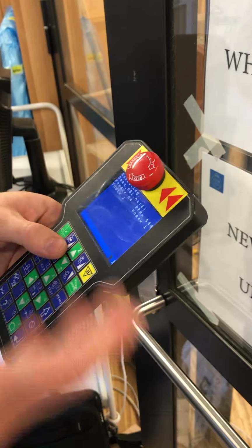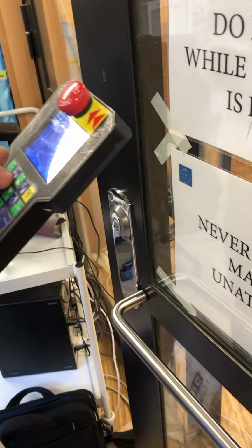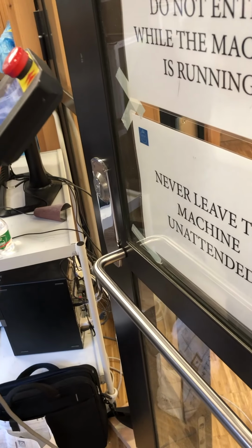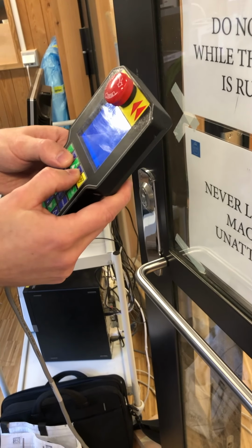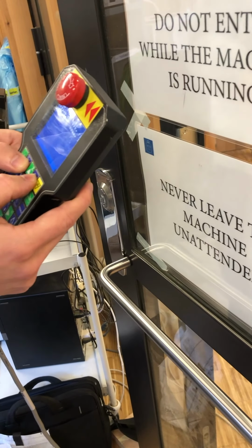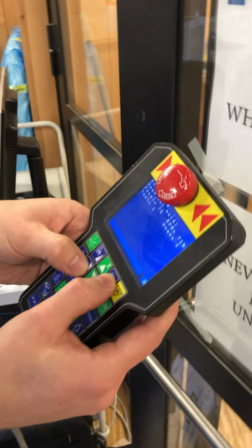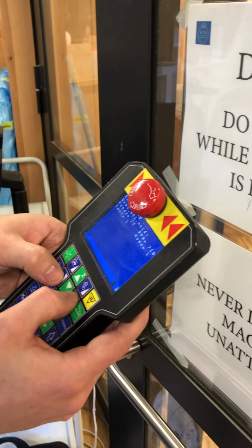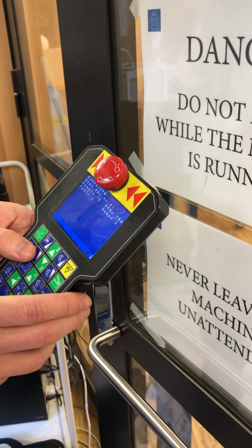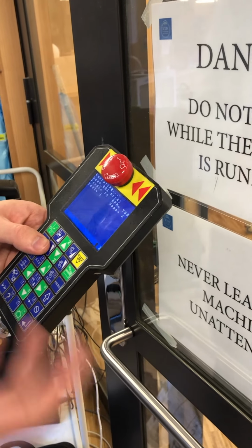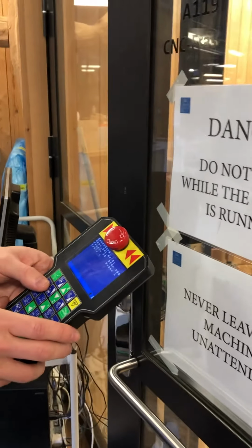Yeah, and you hear that it's another sound, and standing here on the other side of the glass you might be at such a distance that you don't see the surface of the material. But anyway, if we increase the feed rates to about 75% now, but still have the RPM at 7,000, then comparatively the chip load per tooth will be higher than if we would also increase the RPM.